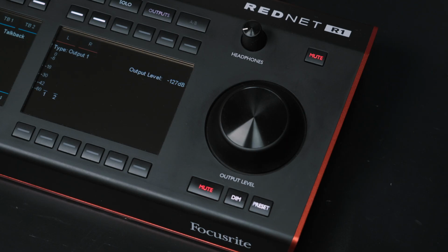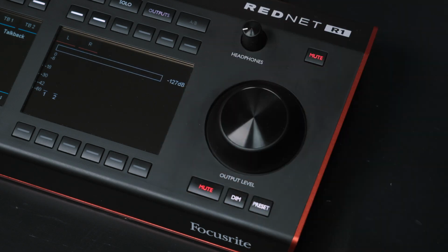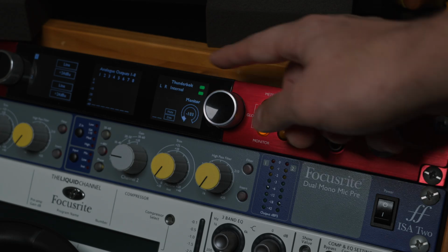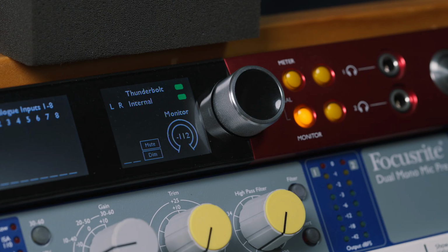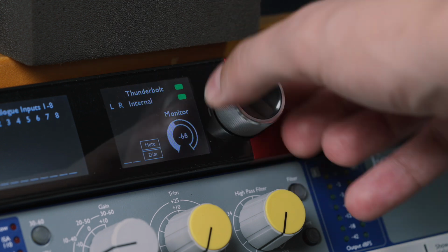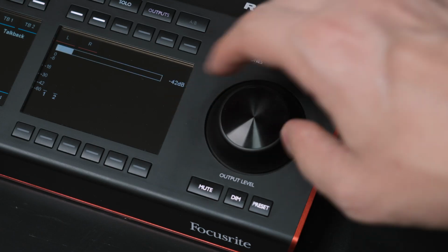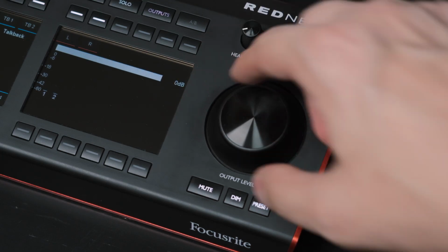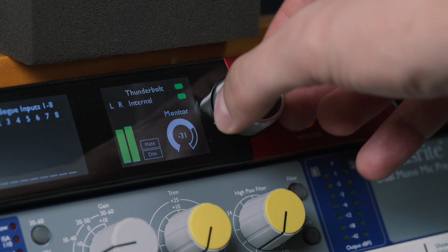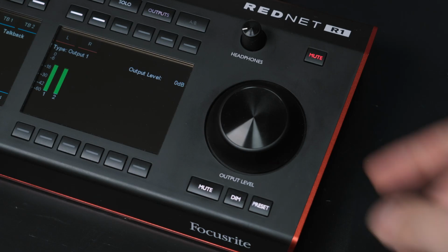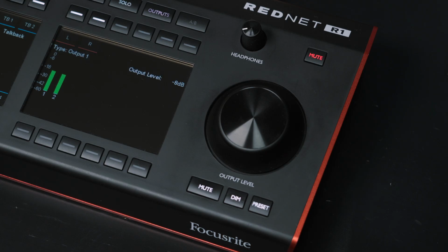Before testing some audio, it's worth noting that the RedNet R1 and Red monitor dials both control the overall output level, which can result in insufficient levels or high sensitivity. The recommended setup procedure would be to set the Red output level lower, but not muted. Turn the RedNet R1 monitor encoder to maximum, run some test signal, set the Red monitor dial to the highest loudness level preferred, then use the RedNet R1 monitor encoder to reduce the level and control further as needed.